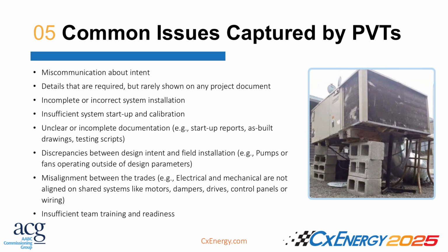Yeah, you can scale it down or up. It depends how confident you think or how complicated the systems are. And a lot of this you might find when you go and actually think about doing the pre-verification test, you might find that you can't do the whole script because something's not ready or a floor's not finished and you can't move air there because it's not clean. Like there's always something. So you've got to kind of make it realistic for what you're testing. But it's so important to have everybody part of that discussion and making sure that you're ready to do it.